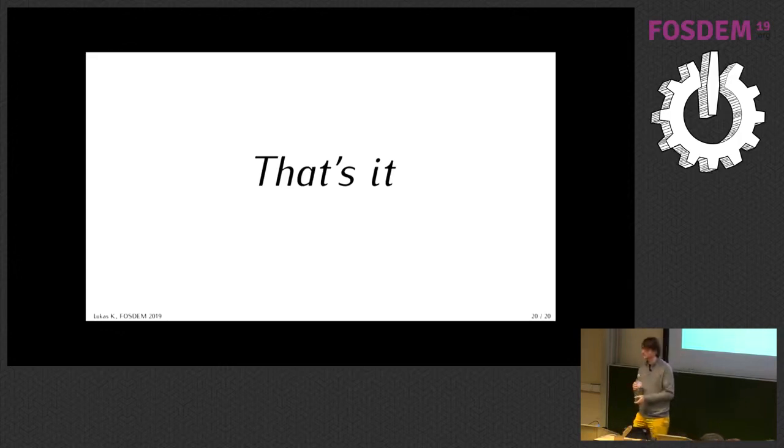Do you plan to implement some way to import library symbols and packages from other EDAs? Yes, I do. The question was whether I have plans for import features for other application file formats. Yes. Importing packages, for example from KiCad, would be a quite natural fit, since the definition of a package isn't all that different. And importing symbols is also doable, since the symbol contains everything that's needed to build a part in Horizon. So using an already existing package plus the KiCad symbol would result in a part, and it's just work. It's not hard, but it just has to be done.